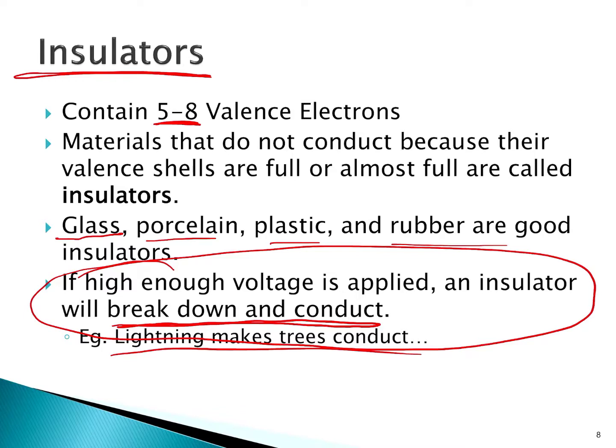And so when we're looking back at this, think of the water analogy, right? If the pressure from that pump was high enough, it would actually burst that pipe, right? And it would mean that the essentially insulating material on the outside broke down, and water was allowed to flow external to the pipe. So the insulation broke down because of why? The pressure was high enough, or the voltage was high enough.